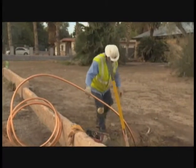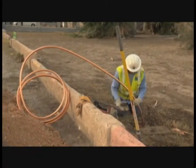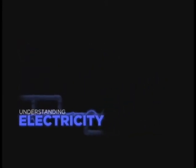Grounding wires are connected to all outlets and metal boxes and then down to the earth by attaching it to either a metallic rod that travels deep into the ground or a water pipe. Poor insulation or a faulty neutral may allow the current to pass through the ground. The shock to utility workers occurs when they install or remove a water meter or cut through metallic pipes connected to the faulty ground. Here is how electricity grounds through humans. Electricity travels to the earth, always looking for an easy path to ground.